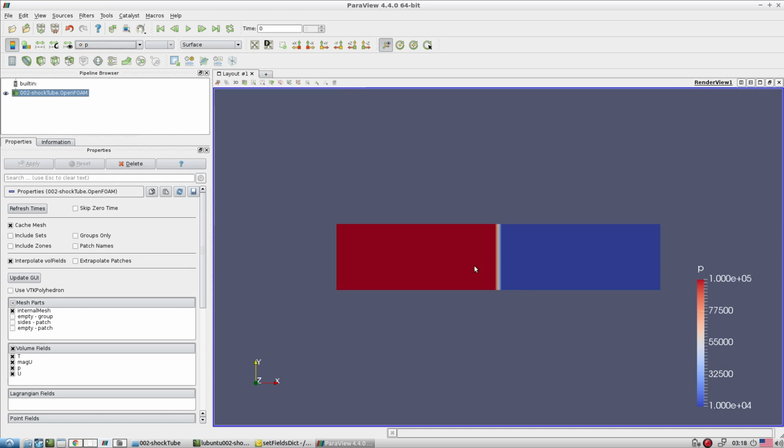This is how we artificially divide the entire domain into parts, where one is the high pressure, high temperature zone, the other is the low pressure, low temperature zone, and then we try to release this barrier. When the barrier is released, it means that on one side there is high pressurized fluid, on the other side there is a low pressurized fluid. So this fluid tries to move in this direction. During that time this discontinuity also tries to oscillate or move in the downstream direction.